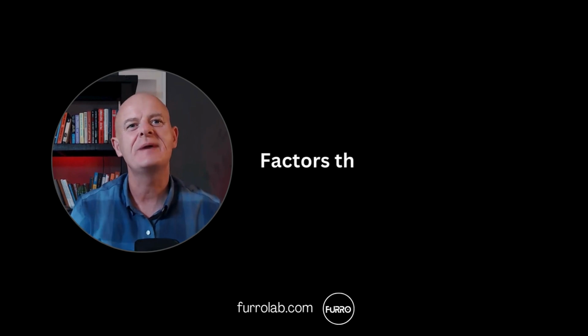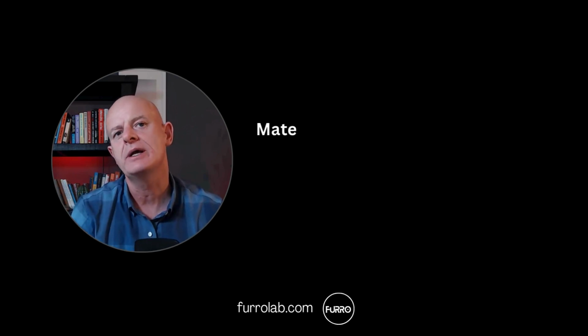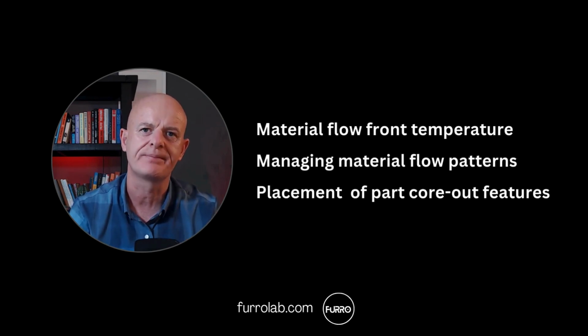What are the main factors that affect weld lines? There are many. A few that come to mind for me are maintaining the material flow front temperature, managing the flow patterns, and the placement of part core out features.